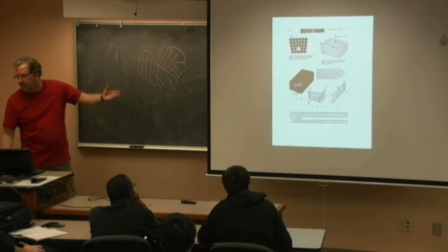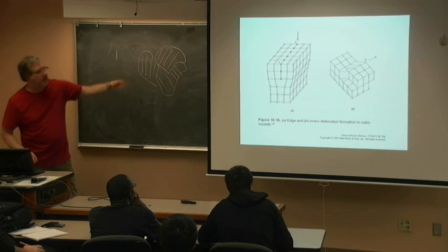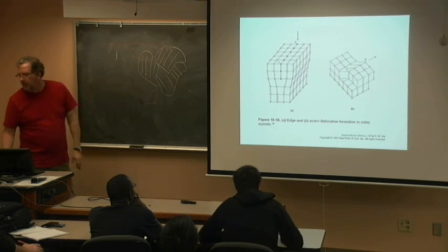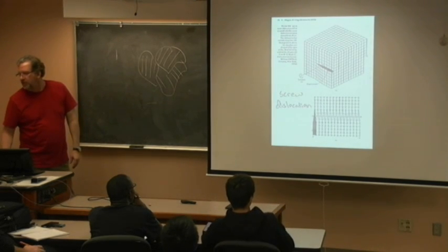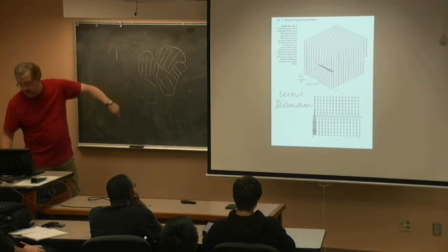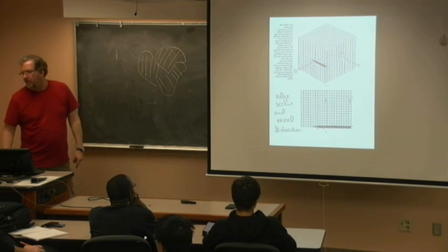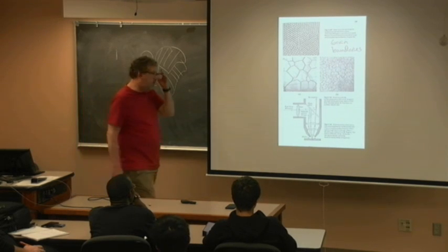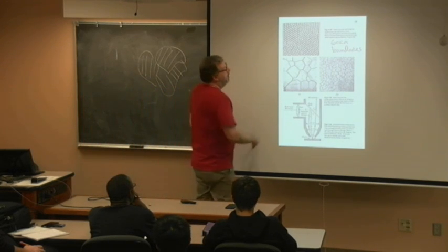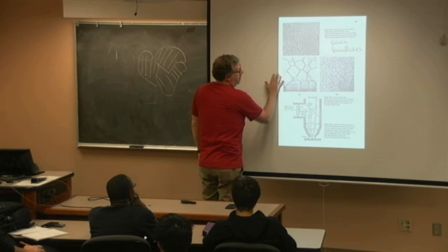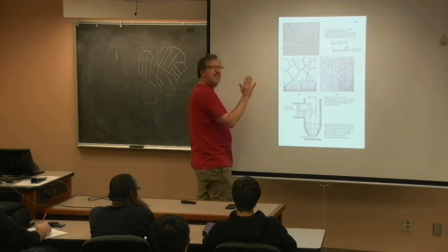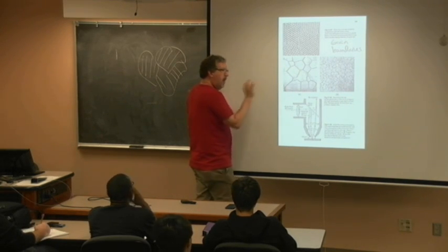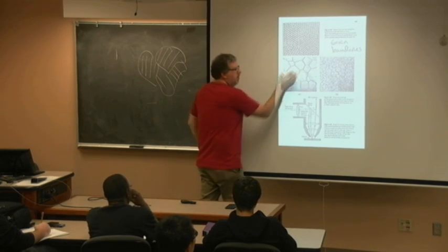Here are some others. There's all kinds of different ways that you can make these incorrectly. Screw dislocation, where it just kind of, we don't have to get into the fine details of them, but you can see. Okay, going back to being able to inspect, here's a polycrystalline material, and maybe I stain etched this, so I applied a mild acid, which attacks all those little grain boundaries.